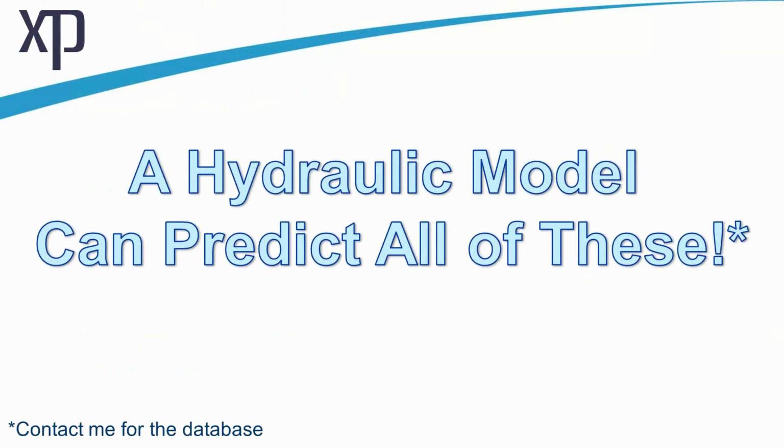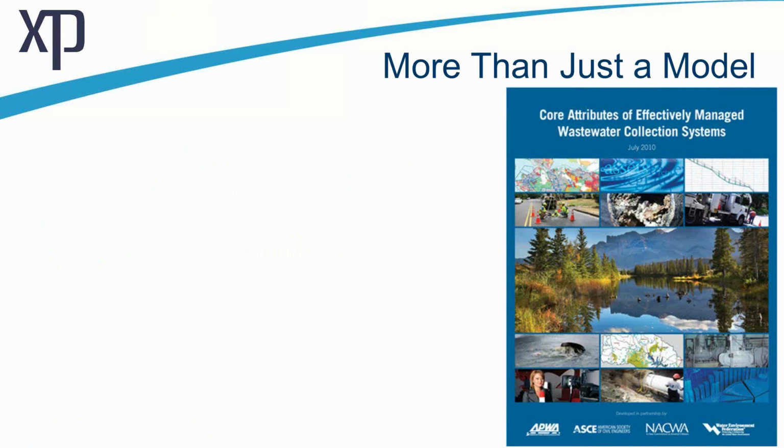And I built something that actually has that all as part of database triggers, that will calculate that based on just results data. So just hydraulic results data and the topology of the network, you can become a little more aware of where these problems may exist. And I think that's really important. Again, not to know exactly every single time, but you have a good idea. And we're beginning to see more and more real-time data, a lot more flow monitoring and rainfall monitoring, both in the duration, permanent installations, as well as the frequency. And we'll cover that again in just a minute.